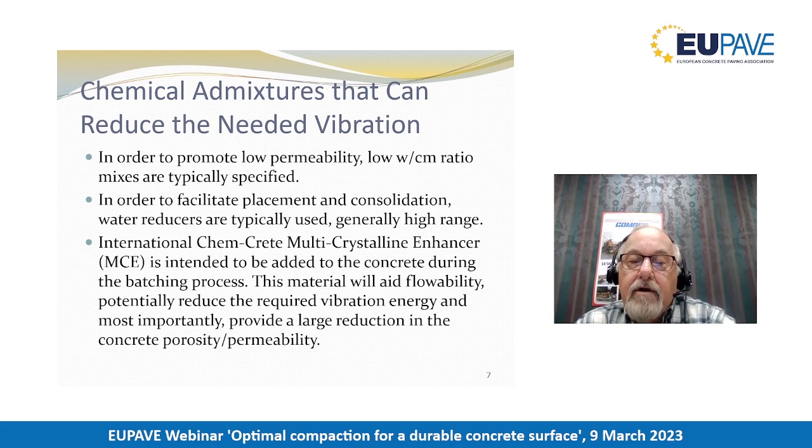It significantly aids in flowability of the concrete. It potentially reduces the vibration energy required, and most importantly, it provides a large reduction in the concrete porosity and permeability, regardless of the level of vibration. So that product essentially crystallizes in the capillary pores of the concrete after vibration.